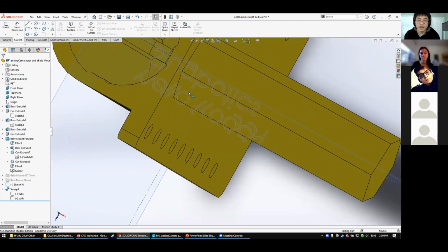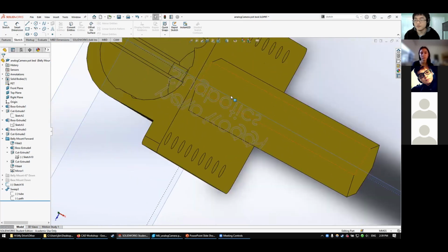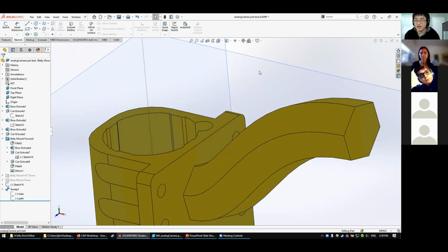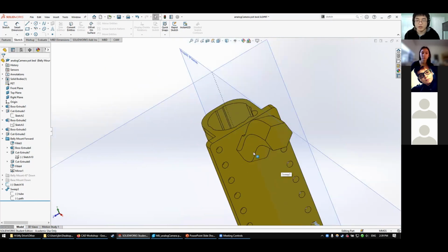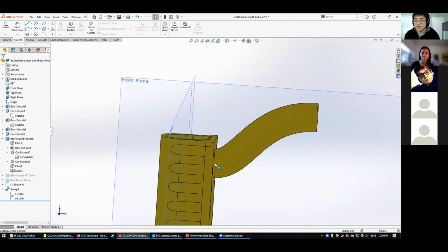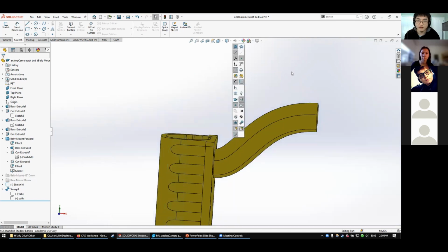And I also aligned the cross section to be intersecting with the front plane so that when I make the sketch on this guy, it is naturally along the center line. Just orient it and plant it in the center of the hexagon. That way the path is coming out of the center and the pipe can be extruded. Okay, let me hide those primary planes again.